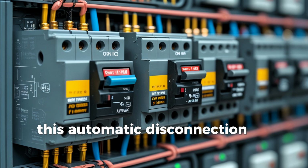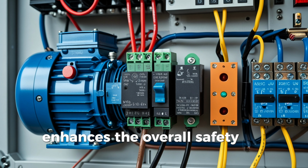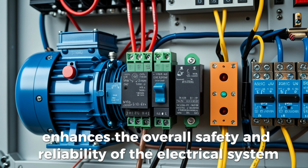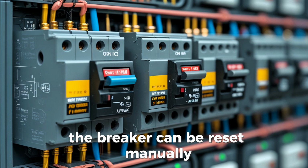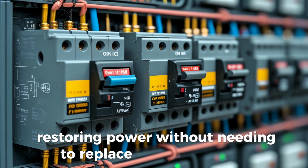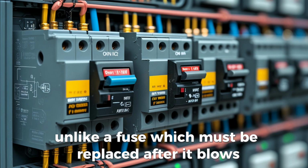This automatic disconnection not only protects the motor and wiring but also enhances the overall safety and reliability of the electrical system. Once the fault is cleared, the breaker can be reset manually, restoring power without needing to replace any components, unlike a fuse, which must be replaced after it blows.